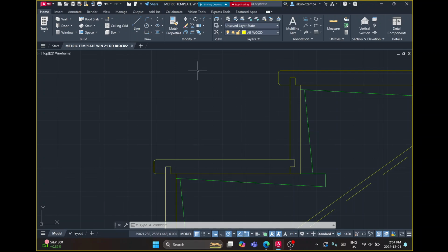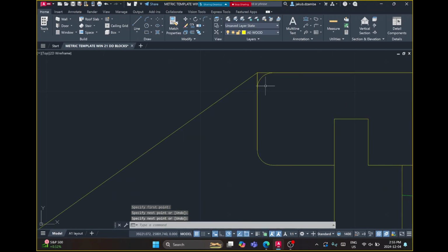of extra work. So I'm going to play it safe, and what I'm going to do is go back to fillet, make sure my radius is 0, enter, multiple, and I'm going to refillet these curves to give me a point. I know it's a bit of extra work, but I think it's worth it, so that we don't have issues with it later. And then I'm going to trim those extra bits off. I don't need them, I just needed it as a temporary thing.